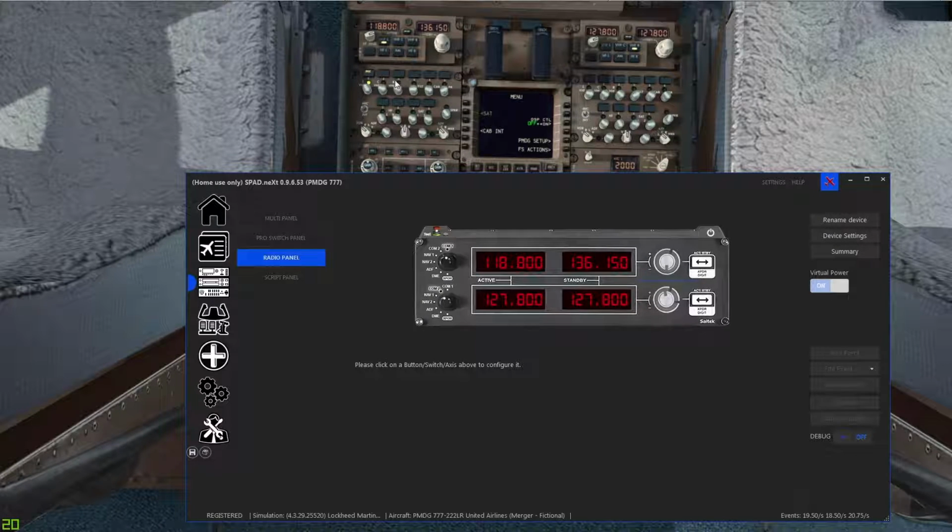we're not listening to the second COM. So if I want to set the second COM frequency, I actually have to be listening to it. And so you'll notice I set up a switch that will enable listening to both, as well as I've got something set up that is going to press the mic. So if I want to talk on COM 2 or talk on COM 1.